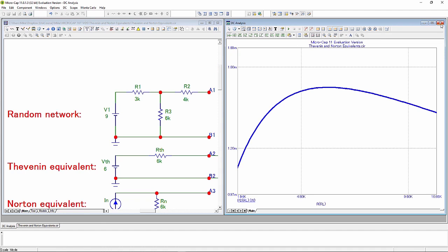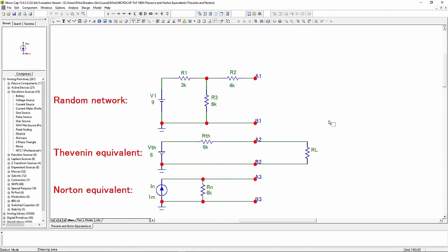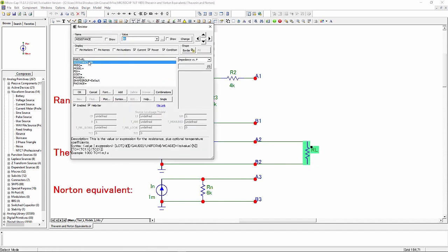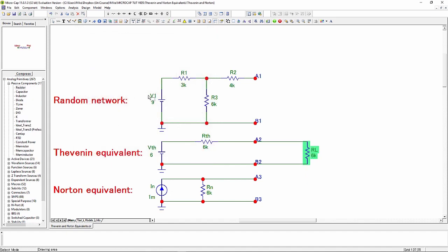Okay, so if I was just to kill that window for the moment and go back to this thing here. So in advance earlier I said to you, I know the value of RL, the optimum value. So I can double click on that. It was actually 6K predictably. So I can click on show for that and then OK.